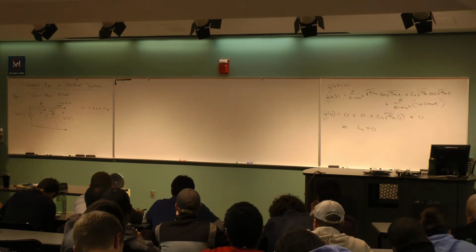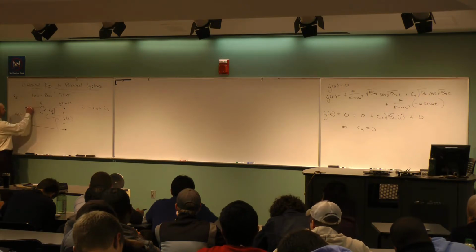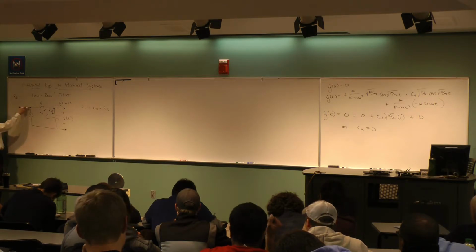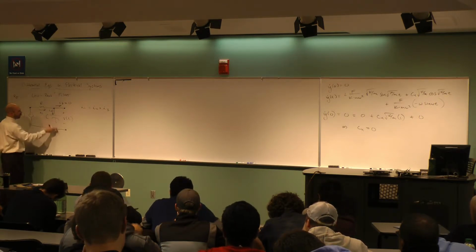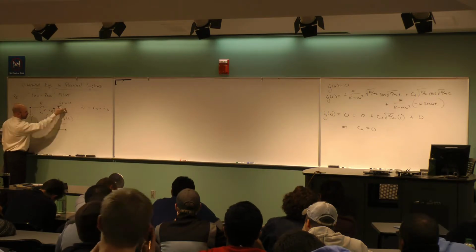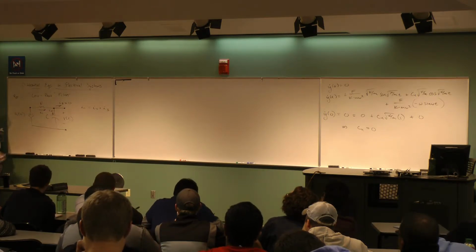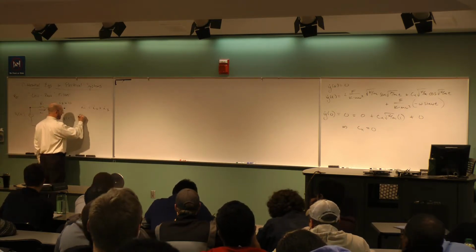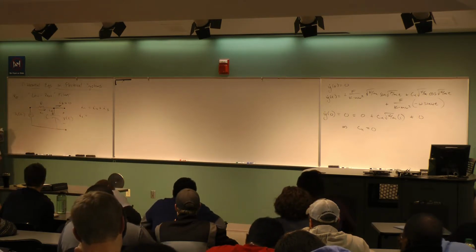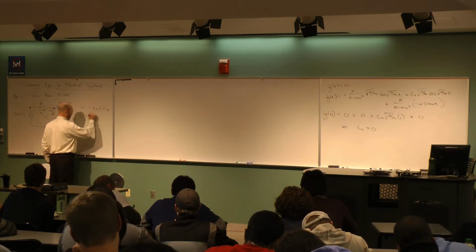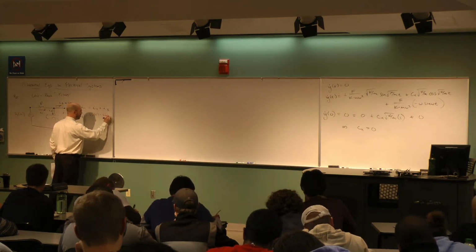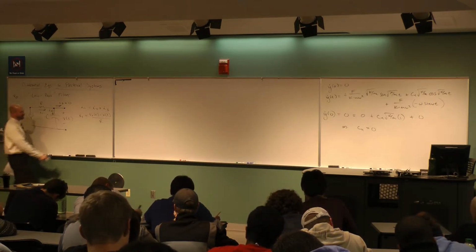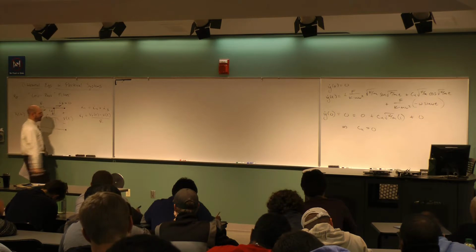Well, the V in V equals IR is the voltage drop between the two points on either side. On the left side, the voltage I have is Vs. On the right side, the voltage I have is the difference between these two points, which is V. So I know what the voltage drop across the resistor is. V equals IR means that I1 is the voltage drop divided by R. So it's Vs of t minus the output V of t, all over R. That's what I1 has to be. Again, this is V equals I multiplied by R.